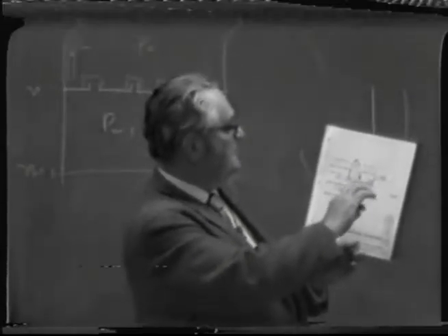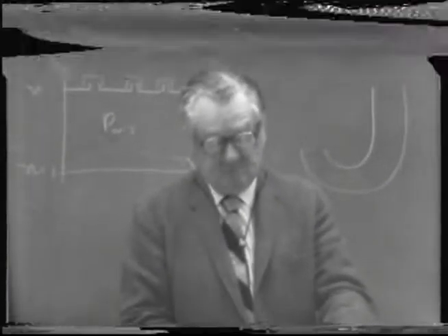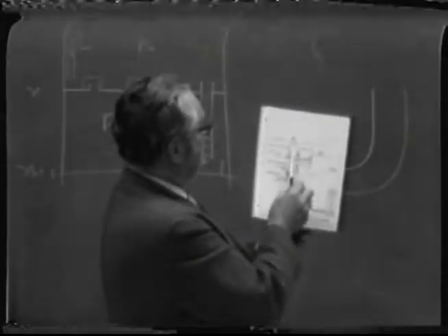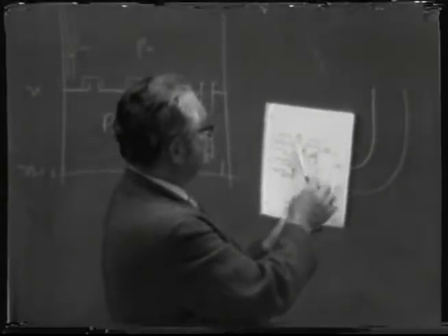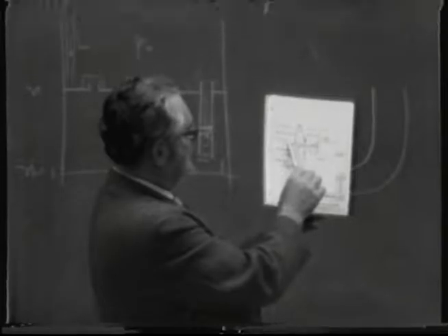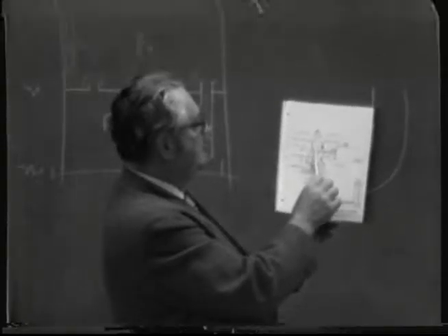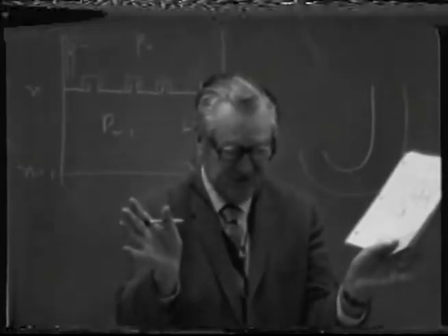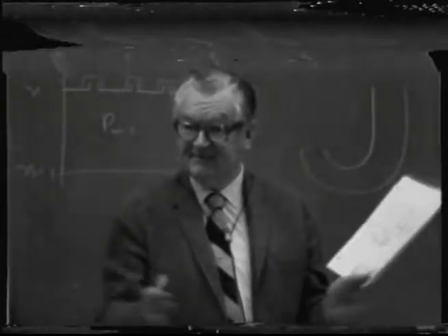So this is sufficient vacuum to cause some of this stillage, the liquid in the stillage, to flash into vapor form, essentially steam. Now, the little dotted line I inserted in here myself is up at the top of this chamber, so any liquid flashed off the stillage flowing into this lower part of the chamber is drawn into this steam flow, and as it passes to the open part of this venturi, or the constricted portion, it is compressed, or in other words, mixed with it.